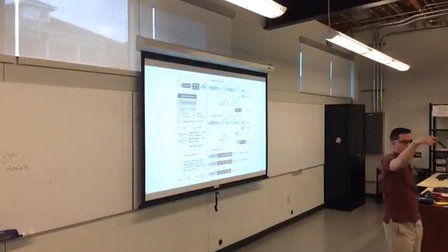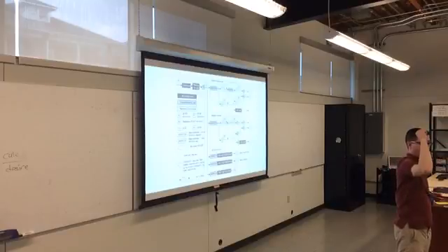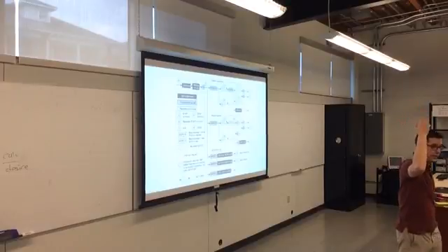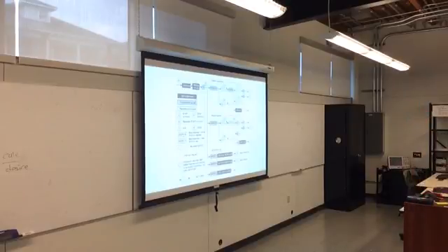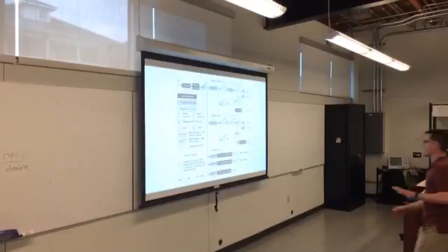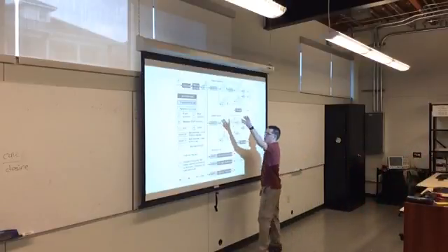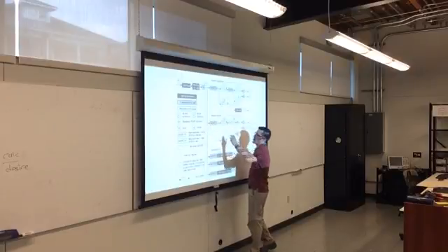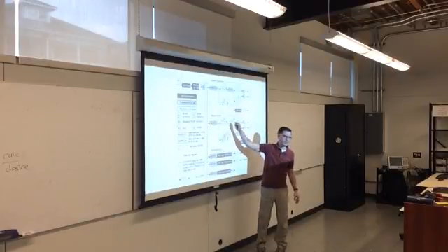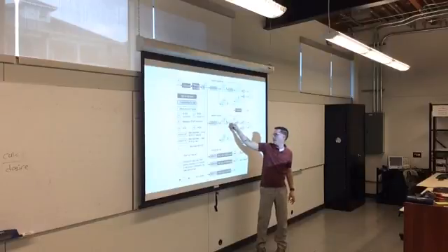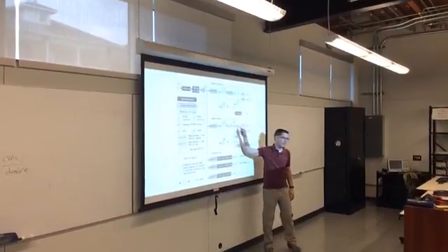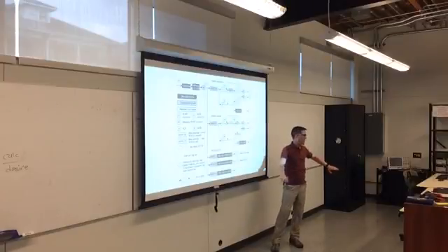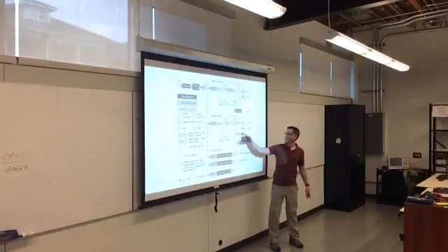The same thing with the receiver. They're generally the same thing, except on the receiver side, you are doing the address plus a read bit. Hey, I heard you, and then the slave device sends the data, and you can either acknowledge, meaning give me more data, or you can not acknowledge, which means I'm done, I've had all the data I want. You can either stop and release the bus, or you can start again and try a new transaction. And you'll see here that this goes to 57, which is that state back there.